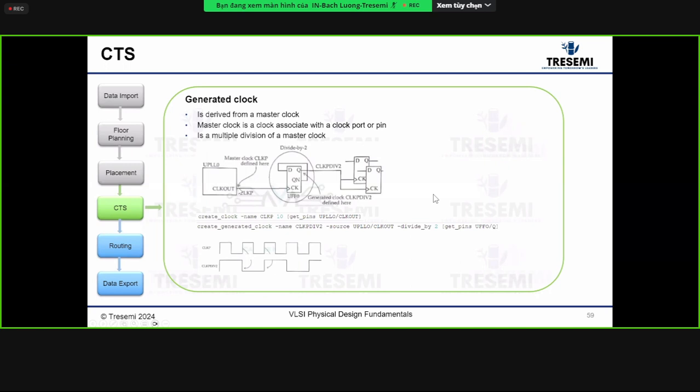Okay, so it's driving a flip-flop, right? And then the QN loops back into the input, and it's driven by the same clock. So you look at the signal, right? When it's active high, it'll latch or change. So that way you get basically a divide by 2 clock. You put another flop and it becomes divide by 4. So that's an easy way to create a generated clock.